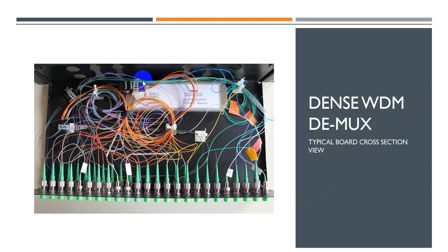The Mux component is this one, and these 40 channels are coming and entering into it, and then finally one output, the line output, goes out, and there may be another for monitoring only. So otherwise 40 inputs, one final main output, and there can be a monitoring output based on the design. In Huawei EX40 we have 2 monitoring, 1 line, and 40 main channels.